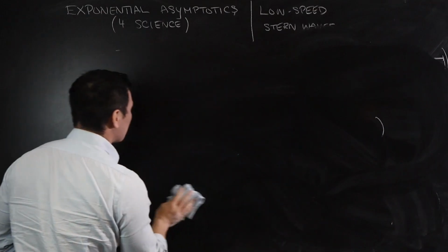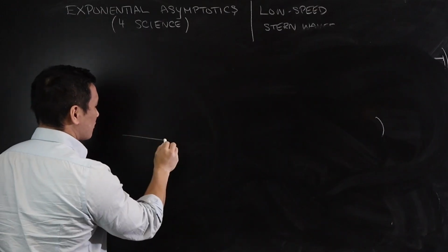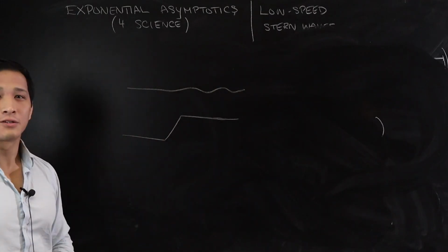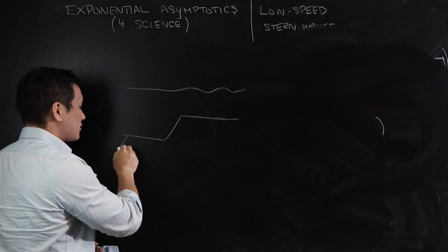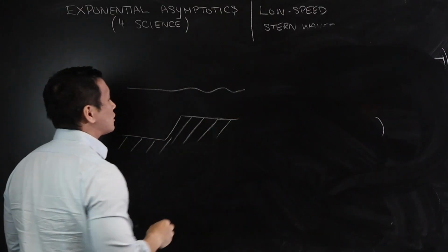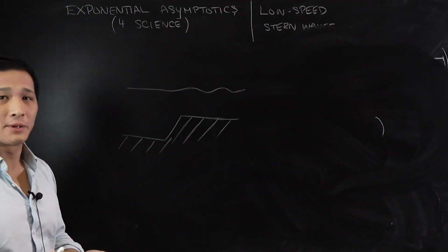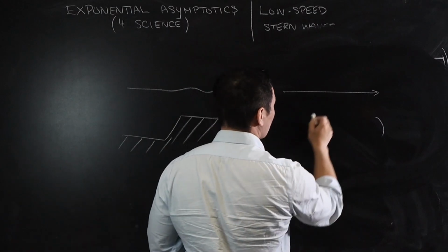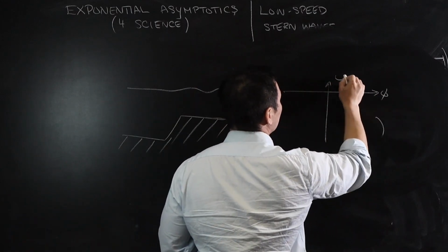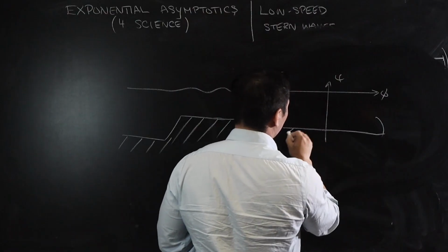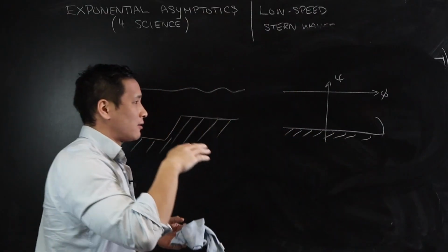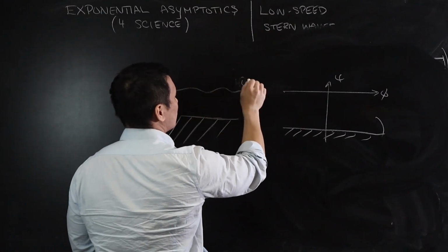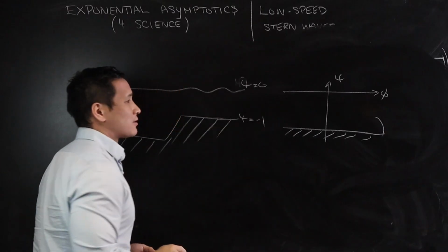How do you do the problem now for a step? Okay, so we were looking at surface piercing obstructions. Well, for the situation of a step, the potential plane looks a little bit different. Instead of being a semi-infinite region that you're interested in, the potential plane is now located within a strip, and the flow is contained within the strip because this is at one value of the stream function, this is at another value of the stream function.